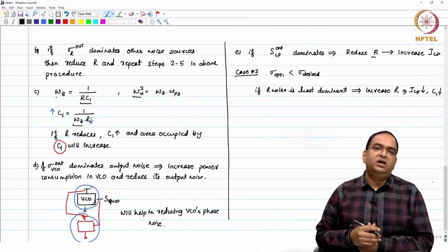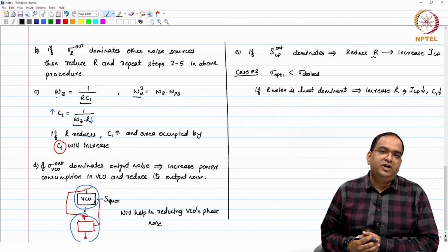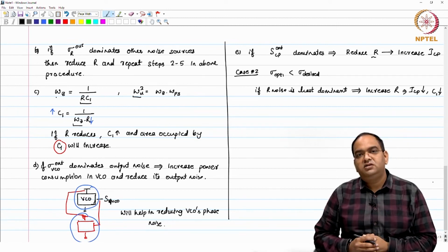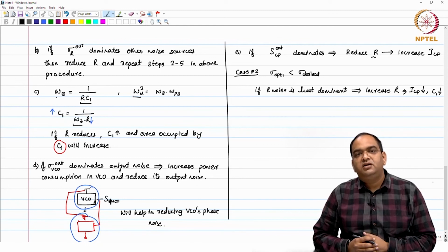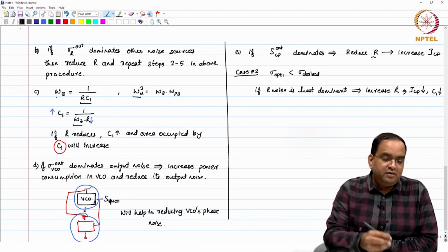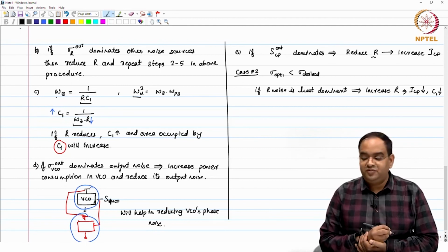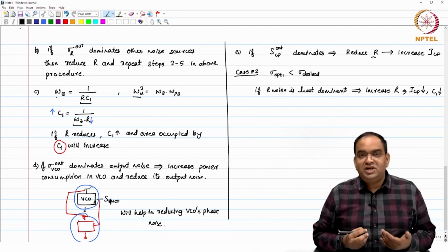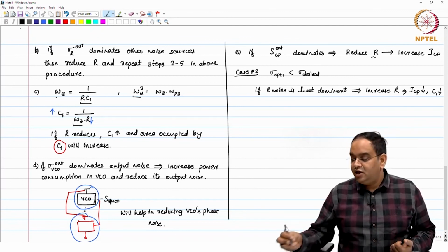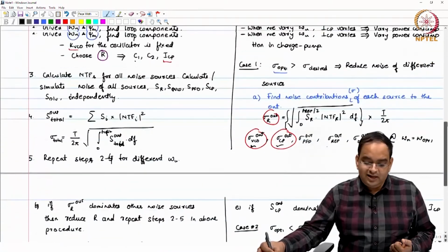If you do not have any requirement from the transient simulation, it is better to keep the phase margin above 60 degree across process corners, right. Then you will see, okay, I will start with phase margin of let us say 70 degree. So, if you start with phase margin of 70 degree, your C1 will be quite large.